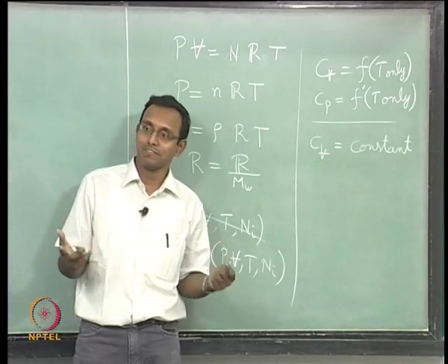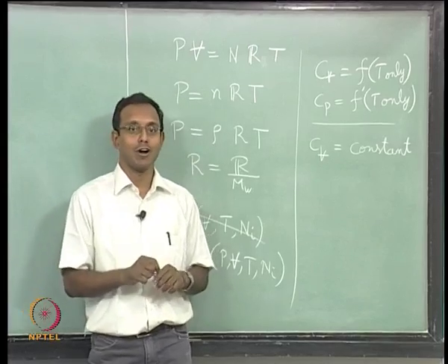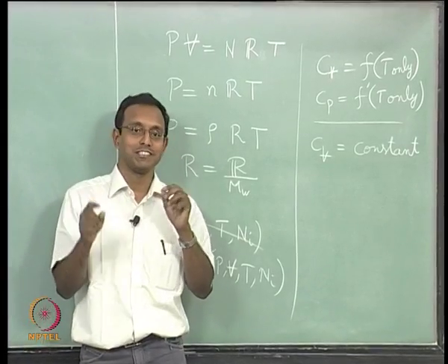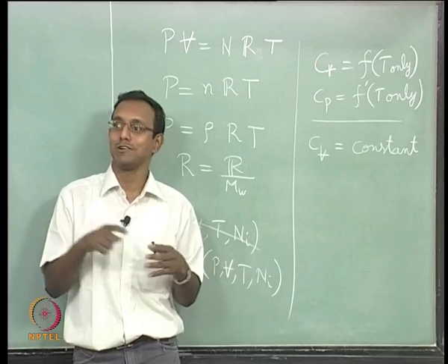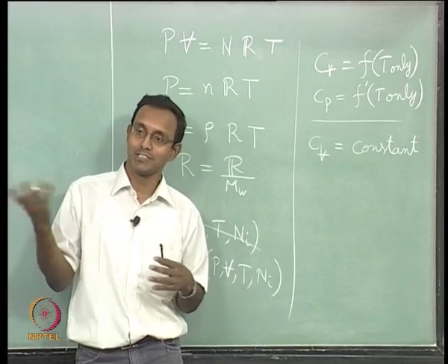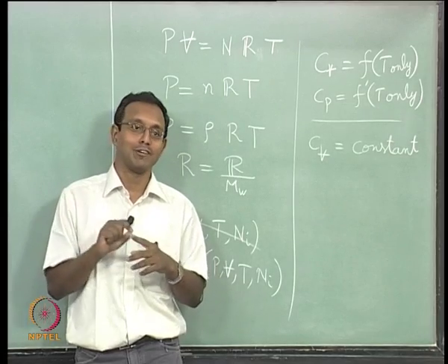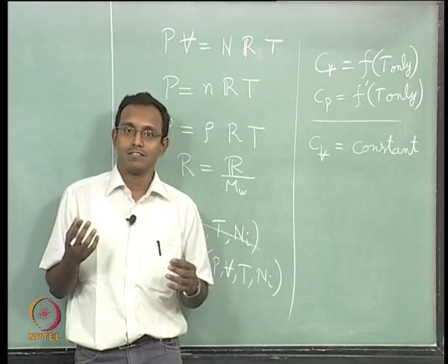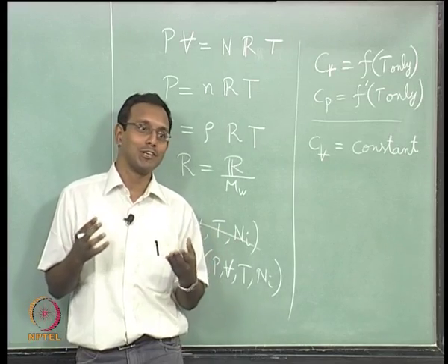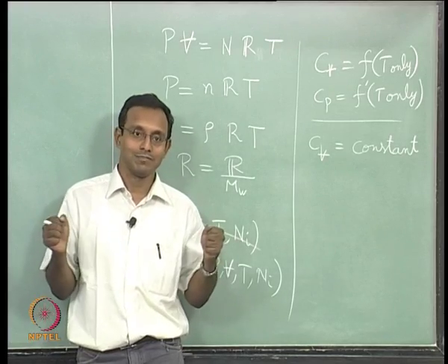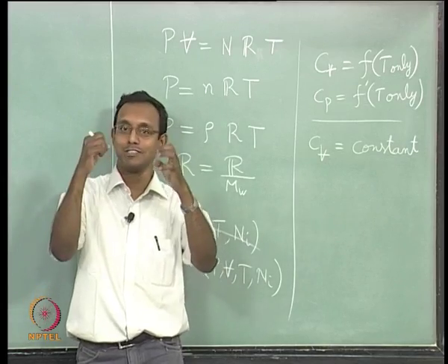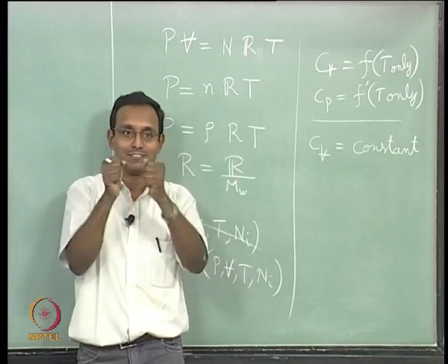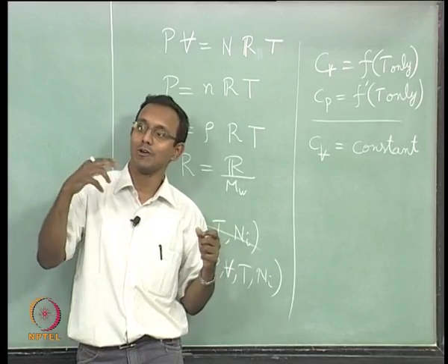But in real life, no gas is calorically perfect for all ranges of temperatures. Every gas can be said to have a particular range, say 100 Kelvin to 400 Kelvin, where Cp is constant. That will happen for most gases. After that range, Cp changes. Why? For low temperatures, the molecules are not vibrating the bonds, but at higher temperatures, let us say I pick oxygen connected with a double bond, the bond gets extended or contracted if I go to very high temperatures.